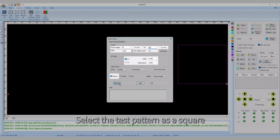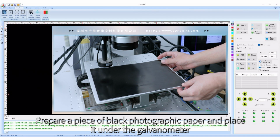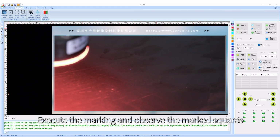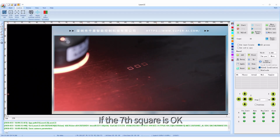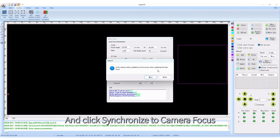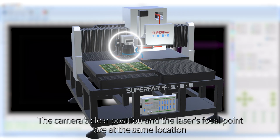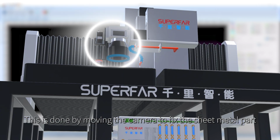Select the test pattern as a square. Prepare a piece of black photographic paper and place it under the galvanometer. Execute the marking and observe the marked squares. Find the square with the best marking result. If the 7th square is okay, then select the 7th test point and calculate the appropriate focal length as 56 mm, and click Synchronize to camera focus. The camera's clear position and the laser's focal point are at the same location. This is done by moving the camera to fix the sheet metal part.